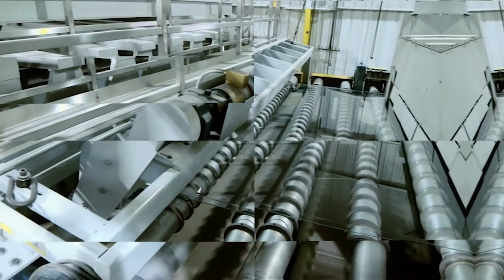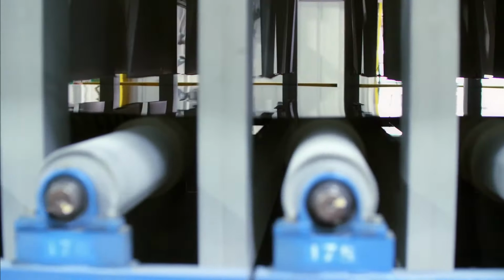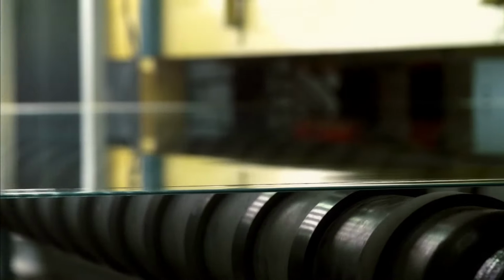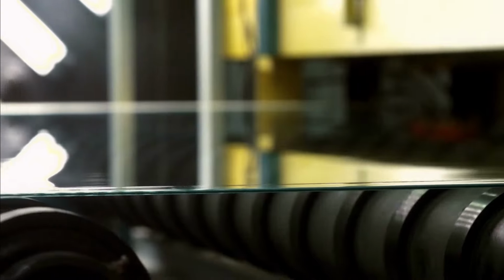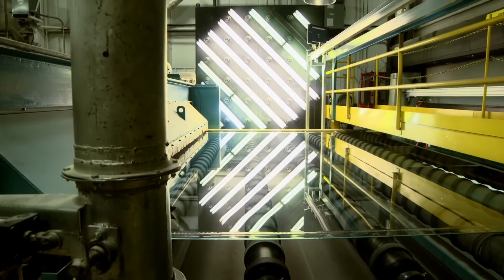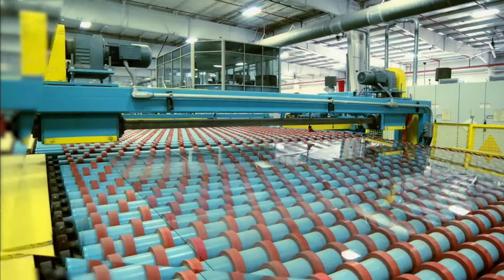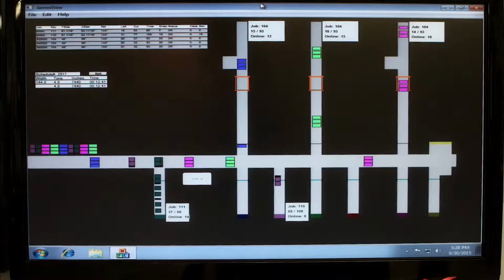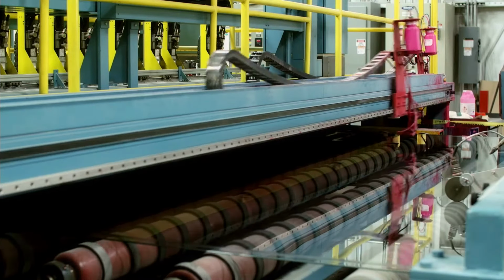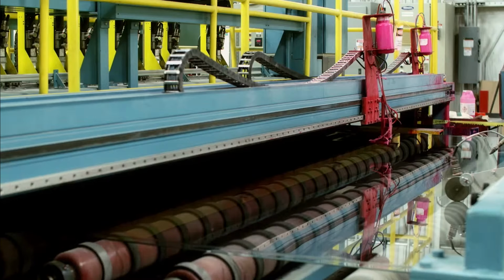Cardinal FG Company in the United States manufactures 600 tons of float glass per day. From the main furnace to the cold end, they produce 20 miles of glass ribbon and use cutting-edge technology to ensure that their output is flawless. Cameras identify uniformity in the glass. Lasers highlight any irregularities along the glass's edge, and professionals do human examination. If any imperfection is found, that section of the glass ribbon is automatically marked and then cut away.